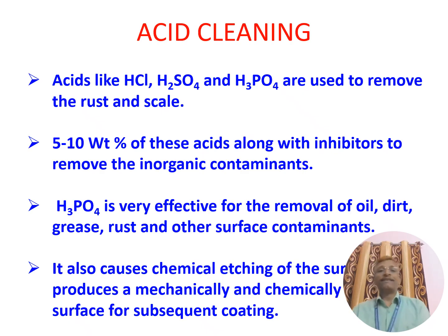And then acid cleaning, depending upon the objects. Acid means hydrochloric acid, sulfuric acid or phosphoric acid, used to remove rust and scale. 5 to 10% of acid along with an inhibitor is used to remove inorganic contaminants. Among the 3, phosphoric acid is very effective for the removal of oil, dirt and rust from the surface.